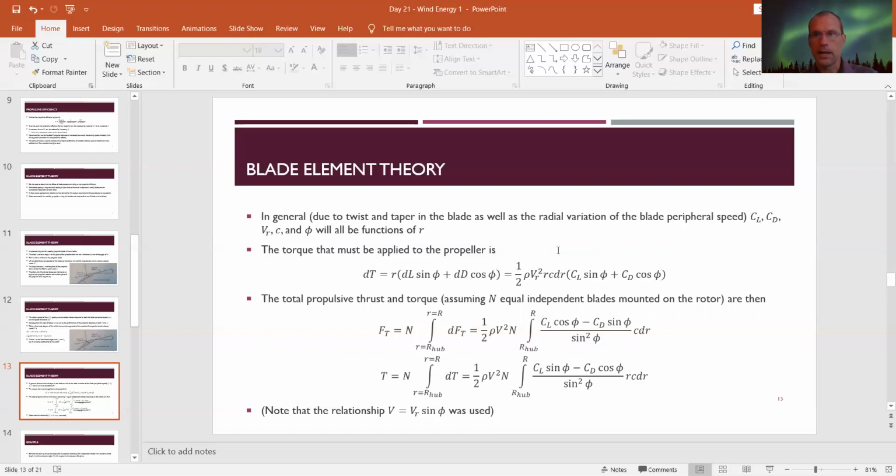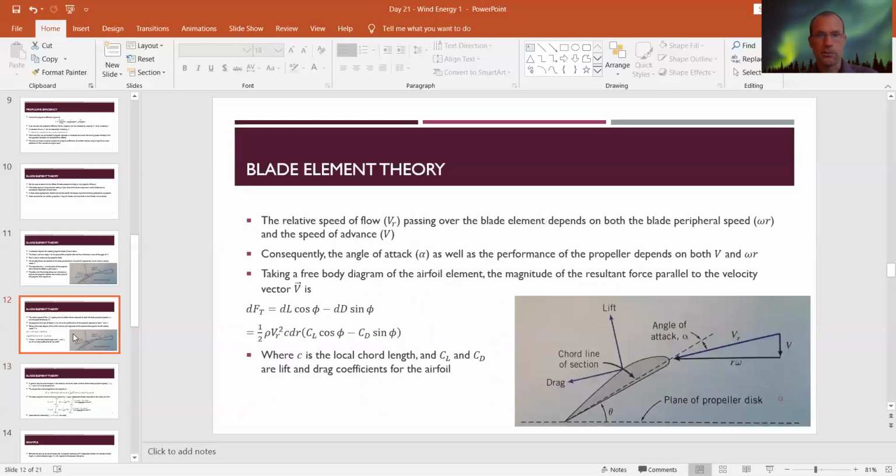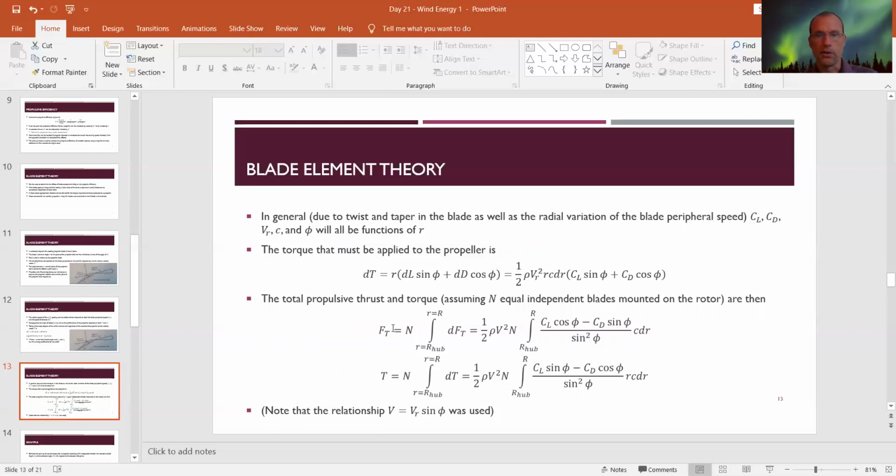Plus sign because, again, right-hand rule, I'm dealing with the torque now. And so it's R cross F officially. And so both of these guys are actually working to spin the blade in the same direction it's going. If we look back at this picture, I'm assuming this guy's spinning around. They're both pushing him. This guy's spinning this way, essentially, to the left. They're both pushing to the left. So they're both creating a positive torque to make this guy spin around. So that's why these are both positive. But in force, there was a minus sign, because that force was in the y direction, up and down.